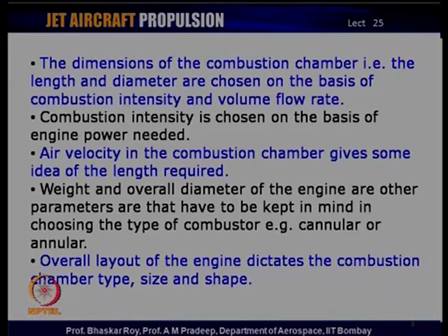So, the overall layout of the engine would invariably dictate the combustion chamber type, whether it is annular or cannular or can type, which is normally not used anymore these days. So, essentially what type of combustion chamber design, the size, the shape, all that is also decided by the overall layout of the aircraft engine, because it has to go on board an aircraft, it has to fit into the aircraft.